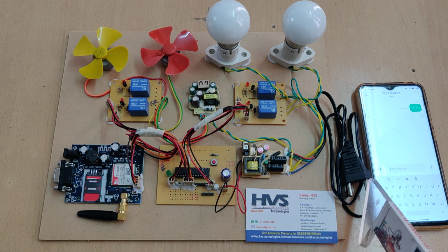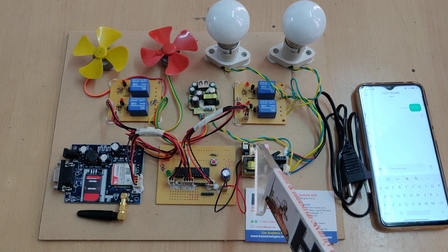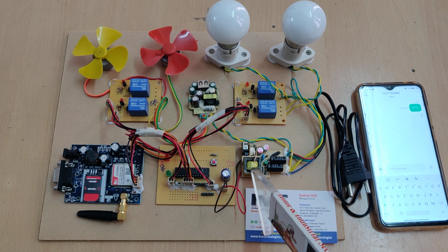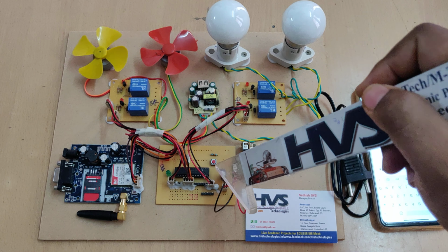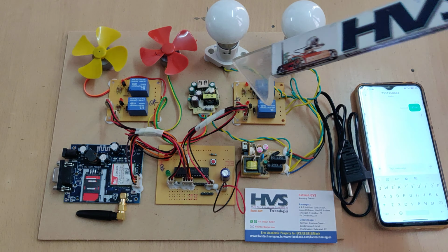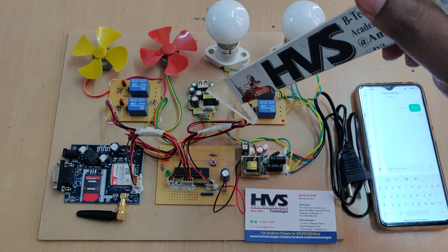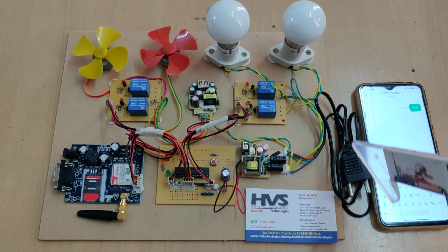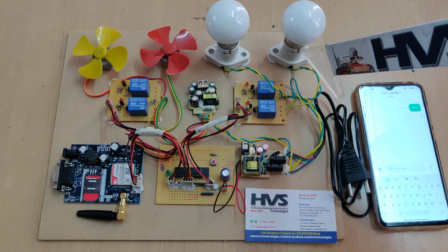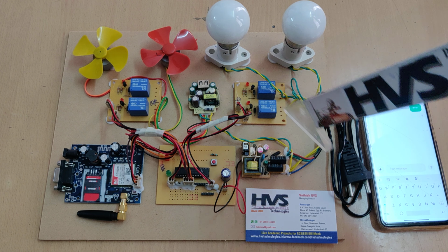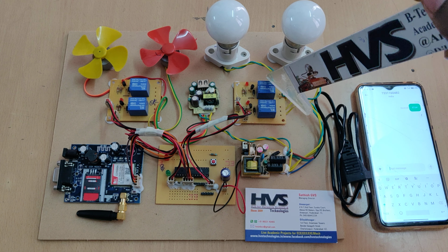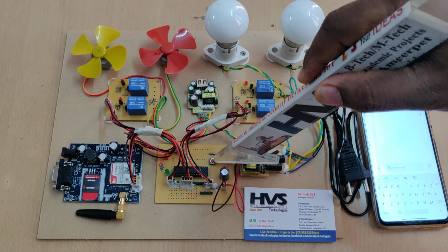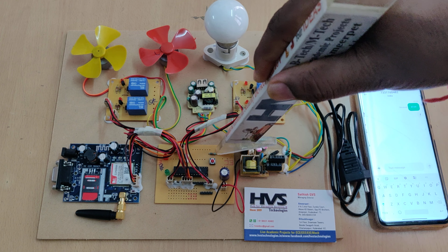And here we are providing 230 volts input to the socket, and there are 2 regulator power supply boards. One regulator power supply board will provide the constant 5 volts to this motherboard as well as to the GSM modem, and this regulator power supply board will provide the 5 volts power supply for these 2 DC motors through the electromagnetic relay. And parallelly we are providing the 230 volts inputs to these 2 loads through these yellow and green wires through these electromagnetic relays.